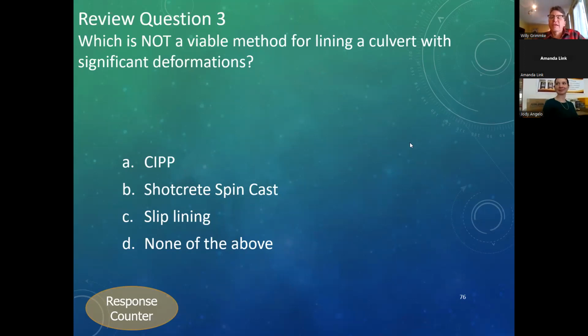However, if you're getting it adequately designed or engineered, it could be, depending on the thickness of the concrete and any reinforcing. DOT recommends shotcrete for inverts that can accommodate low flow channels. Shotcrete can work rather than poured in place.